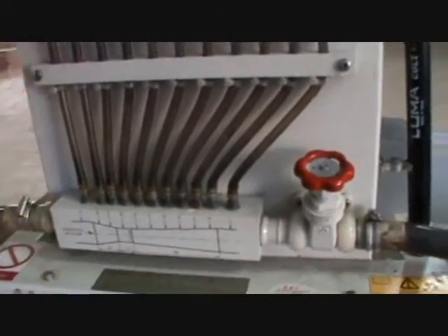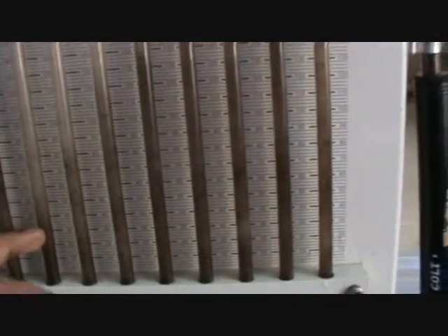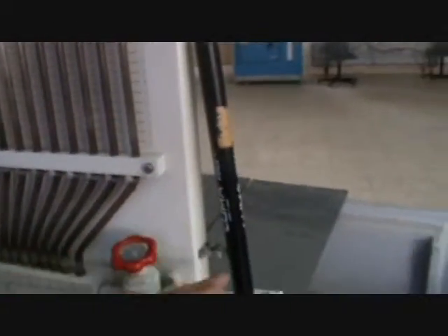So in the second part of the experiment, we have to plot the pressure distribution of the venturimeter along its length. Here we can see the pressure. First of all, it is highest at the first manometer, then slowly starts decreasing up to the throat section, and then again it rises up to the outlet section. After that, the water will flow out from this particular section.